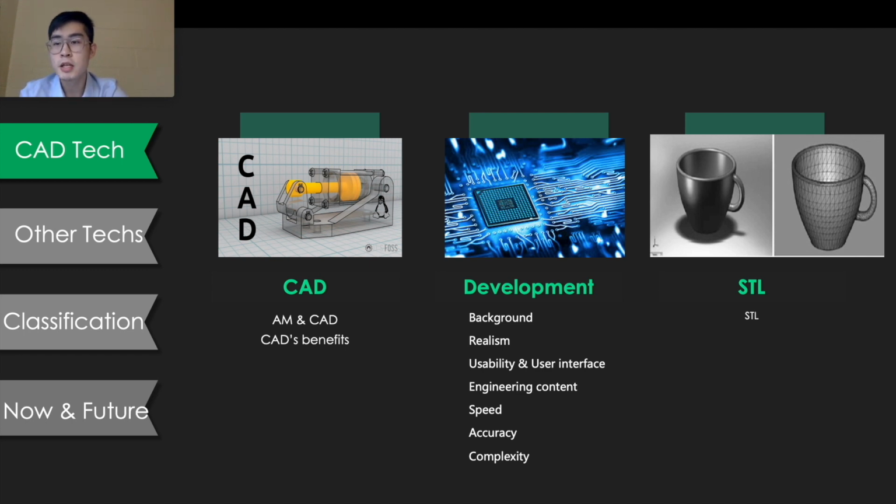The solution is to use the STL file format. It can be accessed easily by all CAD vendors and now is a standard output from nearly all solid modeling CAD systems and has also been adopted by AM system vendors. This picture is an illustration. It uses triangles to describe the surfaces to be built. Each triangle is described by 3 points and a facet normal vector indicating the outward side of the triangle.